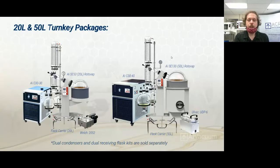And generally, we would recommend that you only fill any of these boiling flasks 40 to 60%, and 20 and 50 liters are the full volume of that boiling flask. So you'd maybe have 8 to 12 liters at a given time in a 20 liter rotary evaporator, or 20 to 30 liters in a 50 liter. But that being said, you can also continuously fill our rotary evaporators with the feed tube for faster evaporation once you have it all filled, and then you would have to drain out the condensate.